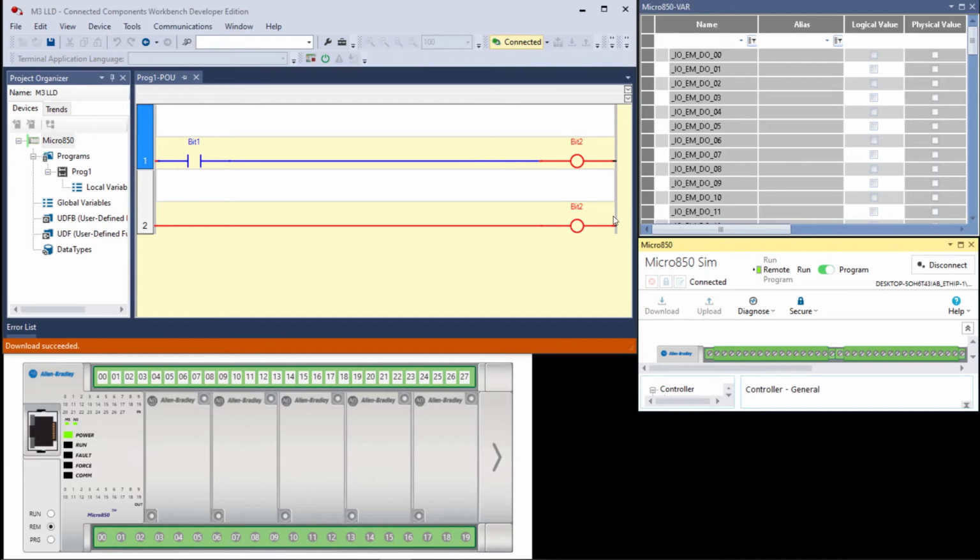Now see, if we swap this all back around, because remember we swapped these 2 rungs, with the rungs swapped, you ended up with the opposite state for bit 2. So if we went back and repeated that, you would see what I'm talking about: when you go to the program mode, it's going to show you the last state that it was in, not what it logically should be when you read the rungs, because they're not executing.